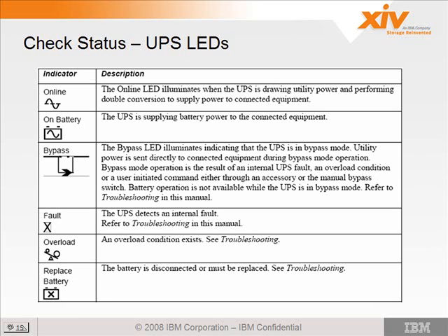What we've seen is the battery charge level gets out of whack in the UPS. What we've done is remove AC power from that UPS that's complaining and let the battery drain until the UPS powers off. Then we reapply the utility power and let the batteries fully charge, and this error goes away. So this is something we're seeing in the field right now. I don't know if they'll be able to fix that with a firmware upgrade or not.